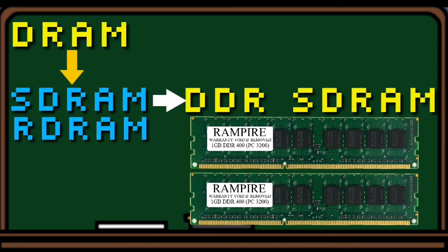DDR-SDRAM, or double data rate SDRAM, is a type of synchronous memory that nearly doubles the bandwidth of a single data rate SDRAM running at the same clock frequency. It employs a method called double pumping, which allows transfer of data on both the rising and falling edges of the clock signal without any increase in clock frequency.